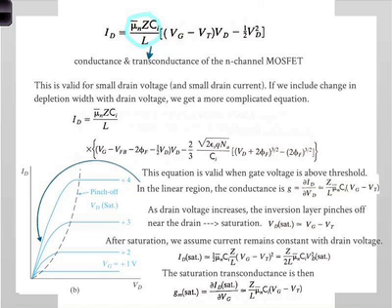Okay? So essentially what it's saying is that you can control the output current in a much more sensitive fashion with the gate. That's basically what I'm saying, by geometric control of the device, right? I can make my channel short, I can make my gate thin. These are things we can control. Materials, less so. Okay? Do you have a question? No.